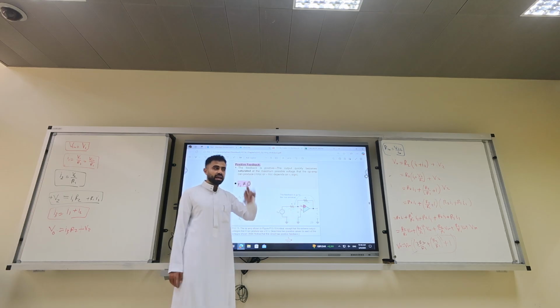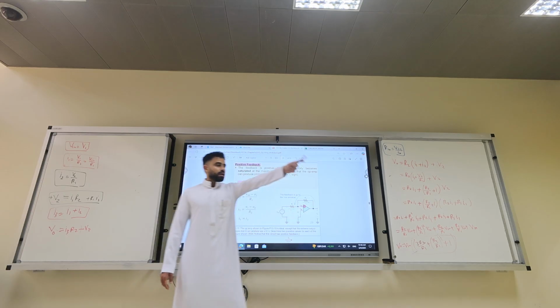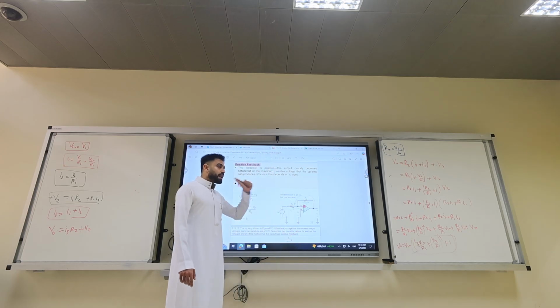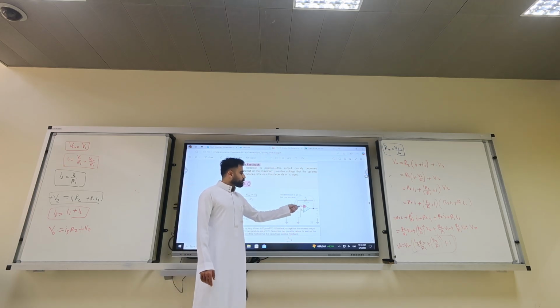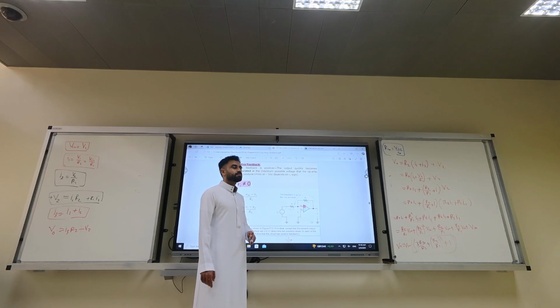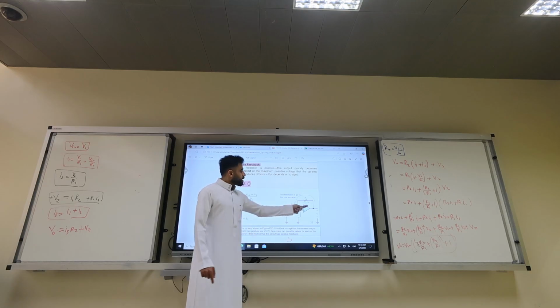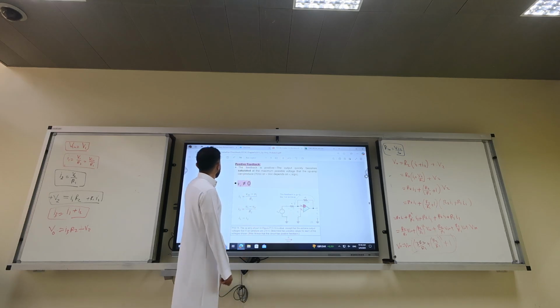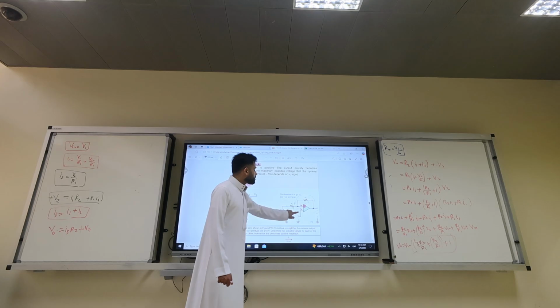Now, the trick here is, in the negative feedback, I told you V positive equal to V negative. Do you think it's the same case for the positive feedback? No. Here we have a positive feedback. This VI, or we call it Vx, is non-zero.